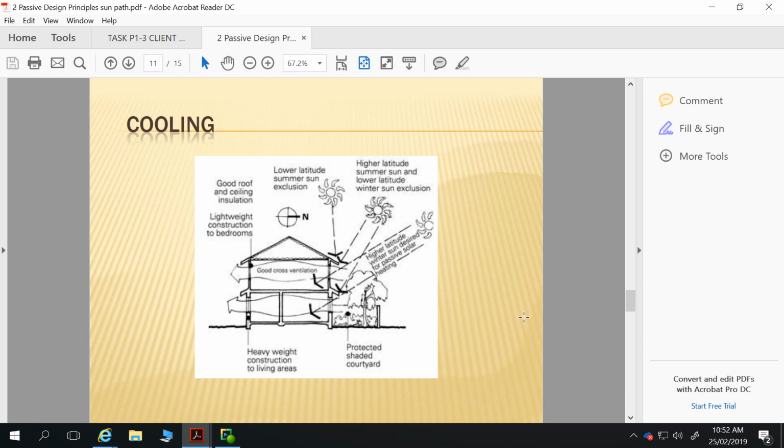Chop our sheeting off. So our sarking goes in between. This is our rafter. It goes in between the rafter and the sheeting, and so it sits on top of those purlins. And you want to create a droop of your sarking like that underneath the sheeting. Now that's for the installer, but also definitely as drafters, if ever you're drawing sarking in, draw it to have a droop, because that's how it works best.